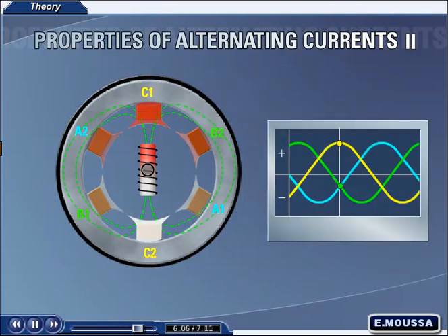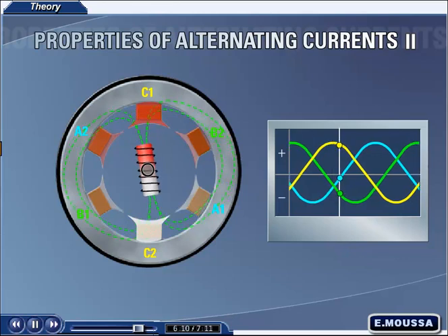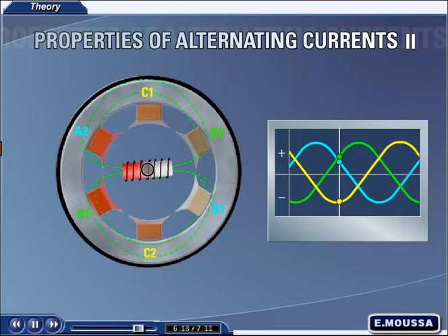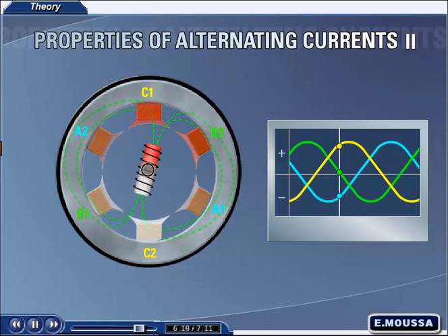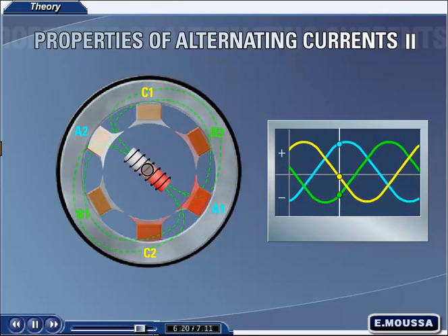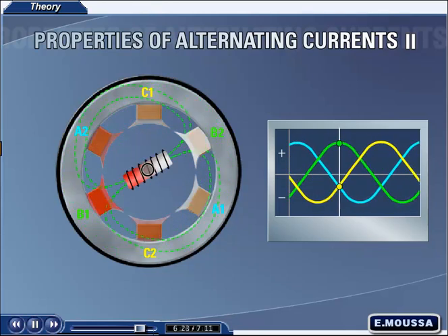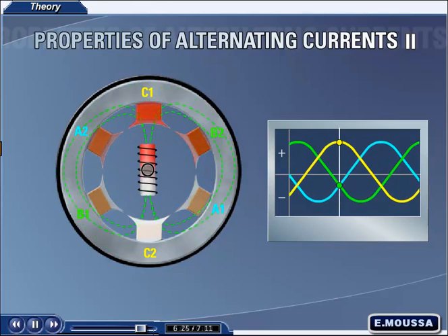As the exciter rotates, the voltage induced in each pair of stator windings will be displaced by 120 electrical degrees from the other 2, corresponding to the physical angular position of the stator windings. The resulting output is the desired 3 sine waves of equal amplitude, but with a 120-degree phase shift between them as shown.